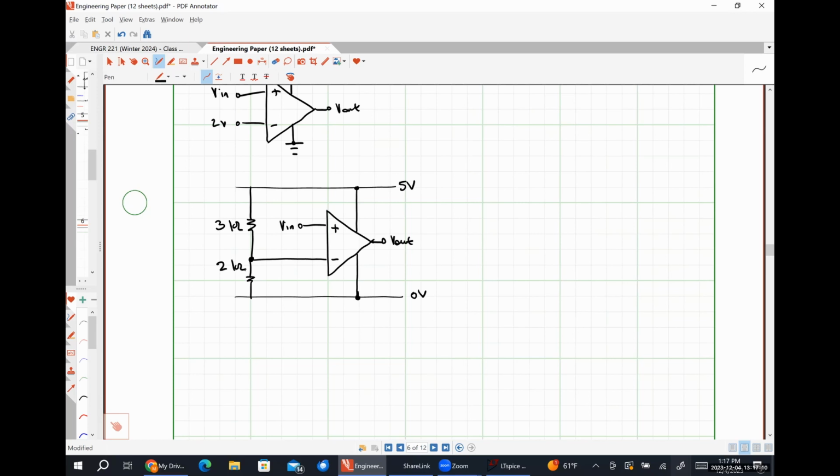2 kilo-ohm here. Another reason we typically use kilo-ohm size resistors is to remind us that the output resistance of an op amp is usually on the order of tens of ohms to hundreds of ohms. So we need something larger than that output resistance so that there's not an appreciable voltage drop over the internal output resistance of the op amp. So the kilo-ohm size resistors is kind of the sweet spot for biasing any practical op amp circuit. So in this class, you will never see me use anything other than kilo-ohm scale resistors for any of the biasing because that's what we do in practice.